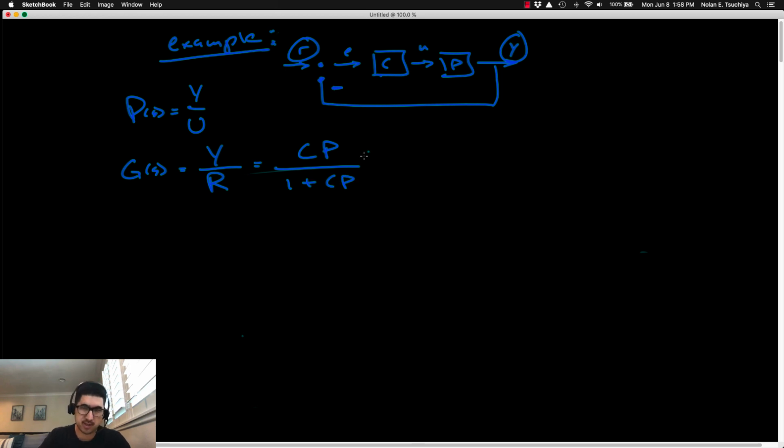So more on this next time. I'll show you how to derive the closed loop transfer function next time, but for the purposes of this example, I just want to show you that there's a difference. Okay, so the open loop plant is just P of s, and the idea is that the open loop plant is fixed. It's just whatever dynamic behavior that particular system exhibits, it's fixed by nature. It's just physics, really, is all it is. The closed loop transfer function...